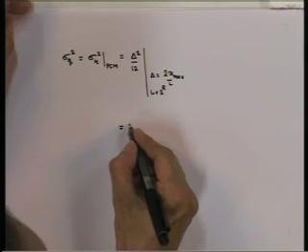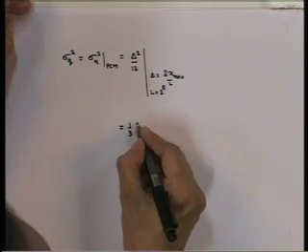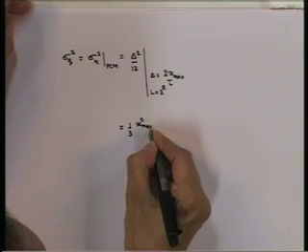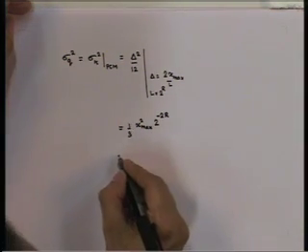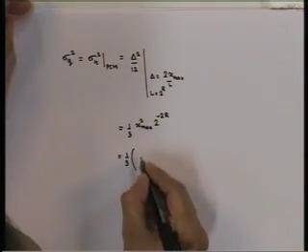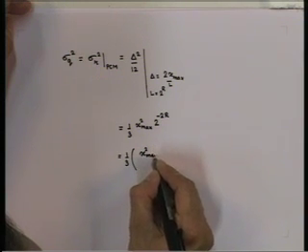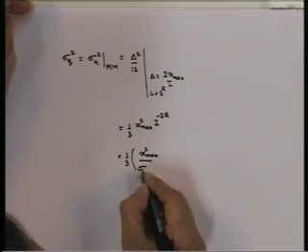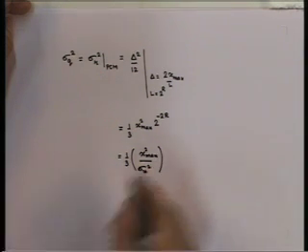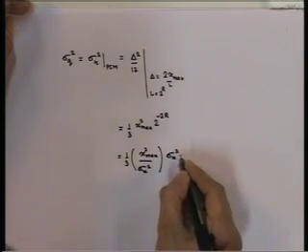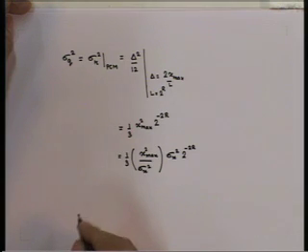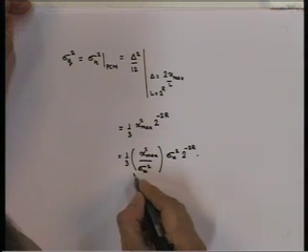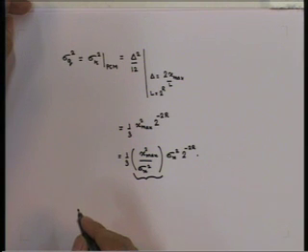So, this can be simplified as 1 by 3 x squared max 2 raised to minus 2 r, and this can be rewritten as x squared max by variance of the input, multiplied by variance of the input times 2 raised to minus 2 r. Now, this quantity depends on the distribution of x.